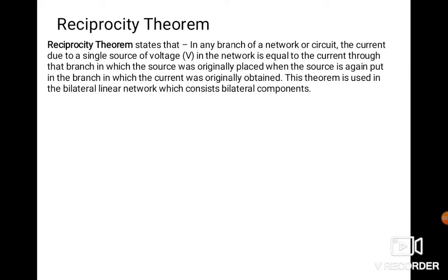For better understanding, let us take the example of a telephone line between two subscribers, X and Y. If the telephone circuit comprises permissible elements, then the reciprocity theorem permits us to assume that the transmission from X to Y is identical to that from Y to X. This general specification is used in practice in the design and testing of the line.